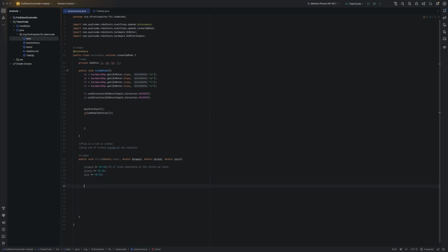So now that we have this done, we basically have to stop and reset our encoders. If we don't stop and reset our encoders, it's gonna keep adding up. Let's say our starting position was 200, the initial position. If we don't reset our encoders, and I just want you to move 300, I'm already at 200, so how much do I need to get to 300? In reality, if we tell it to move 300, it's only gonna move 100 ticks because it's already at 200.